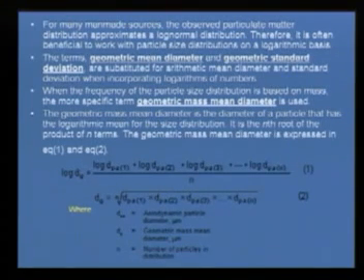You can find out, take the log of each of the particles, and then take the simple arithmetic average. What it is giving you is the log dg, and what I am interested in is the geometric mean. So that is how you get the geometric mean. You can come from here to here. The interesting thing which I want to share with you is, suppose